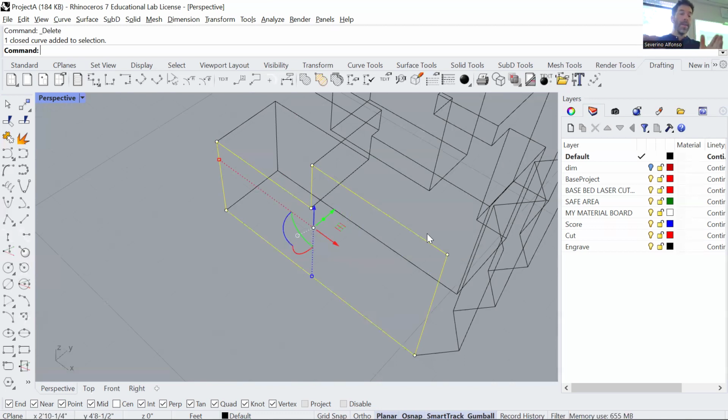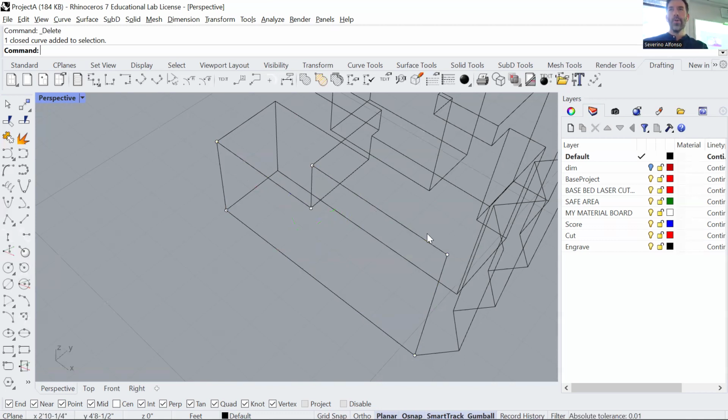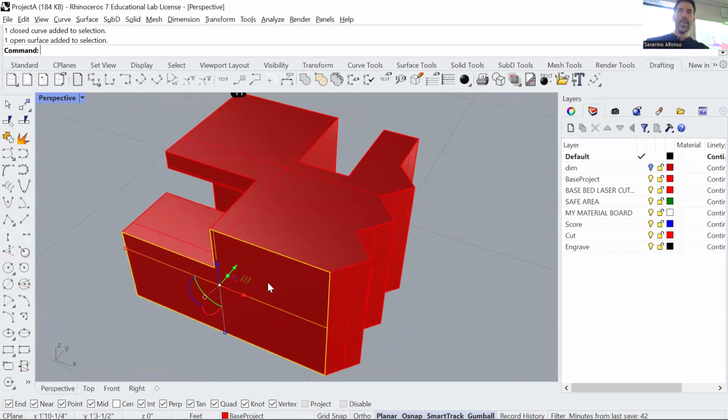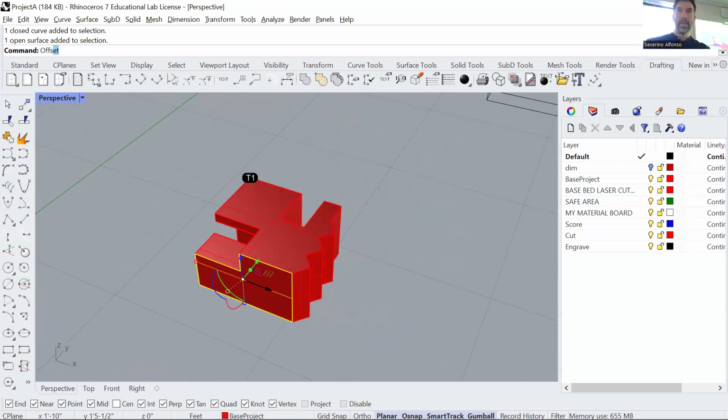Okay. There are also ways to do this connection. Basically, you do a castle shape connection for one of the pieces, and the same castle shape but shifted in the other direction so they match perfectly. I don't know if that makes sense, what I'm saying. To do that, you need to do a little bit of work here. You probably need to do an offset surface.